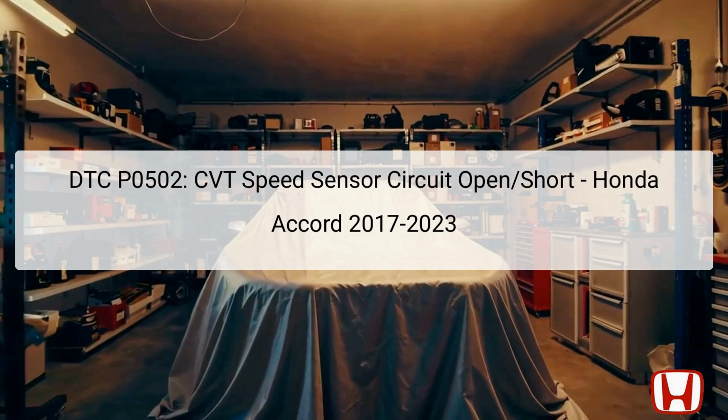The DTC P0502 indicates an issue in the continuously variable transmission (CVT) speed sensor circuit, specifically pertaining to an open or short in the electrical circuit. This code occurs when there is no electrical signal being received by the transmission control module (TCM) from the CVT speed sensor. Unlike mechanical issues, this code strictly points to electrical faults that disrupt the functionality of the speed sensor, which plays a critical role in informing the TCM of the vehicle's speed.